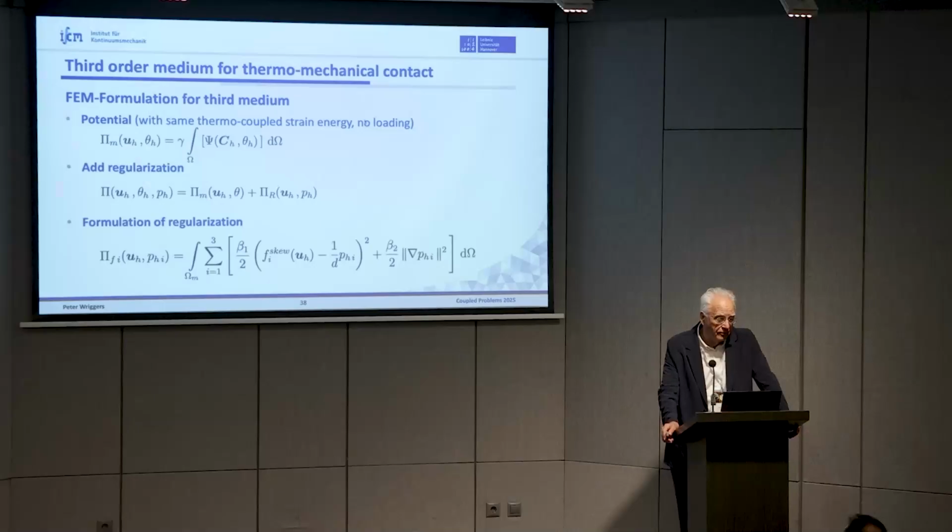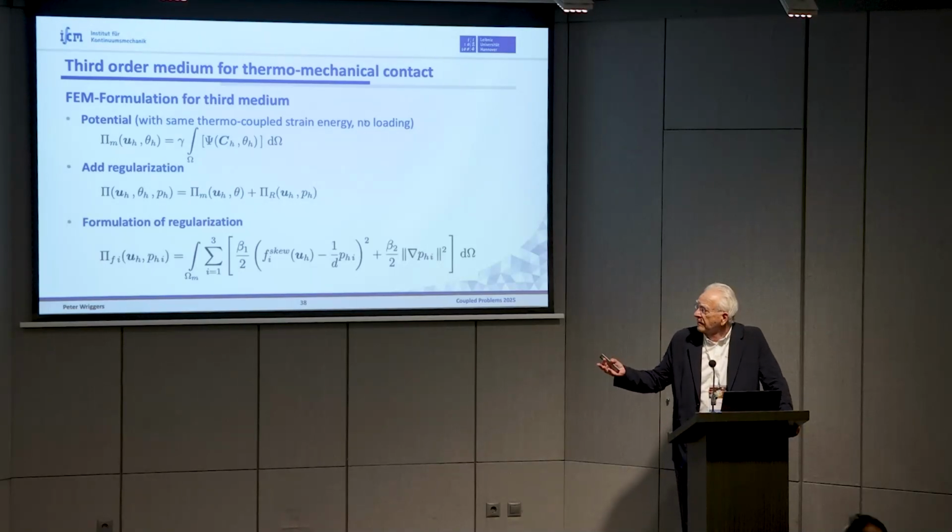The regularization does not have to be given for the thermal part. It only has to be given for the mechanical part, because the thermal part is just the heat conductance, which does not depend on the deformation, besides the pressure dependency of the conductivity. So this is basically the same.